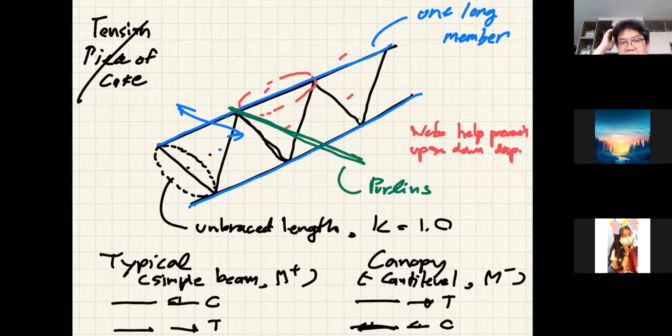So let's say I have the purlin at every other panel, where the triangle can be called a panel. Let's say I have another purlin here. You will see that this truss will be free to move out of plane from this point to that point.